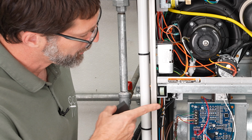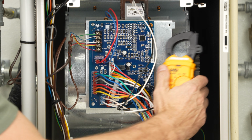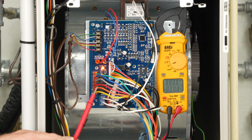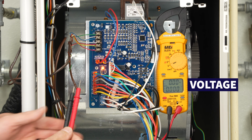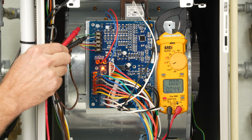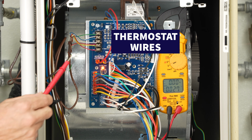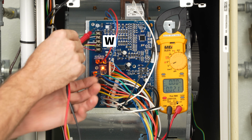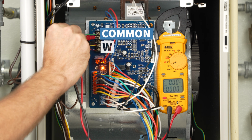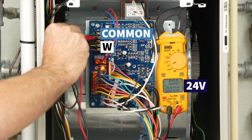We can remove that door. We want to close the door switch with a magnet or tape. And we're going to have our multimeter set on voltage. So we're going to measure our voltage for alternating current. And basically, right here is the thermostat wires. We should have a call on W in order to turn on. So we can measure between common and W, and we should have 24 volts if the thermostat is telling the heat to turn on.